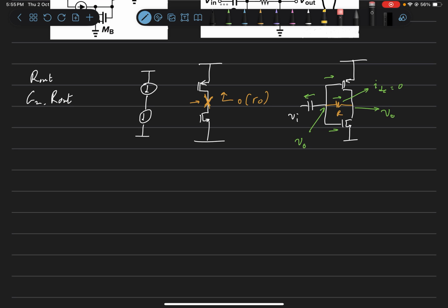But we would need them to be high impedance since we need a higher gain. So how do we solve that problem? Because now since they are diode connected, they'll offer low impedance of the order of 1 by gm and will not be able to have high gain amplifiers. Otherwise we would just have used two diode connected transistors like this, directly shorted by a piece of wire. Why are we using this resistor over here is the answer to the question of why the circuit still has a gain of the order of R0.